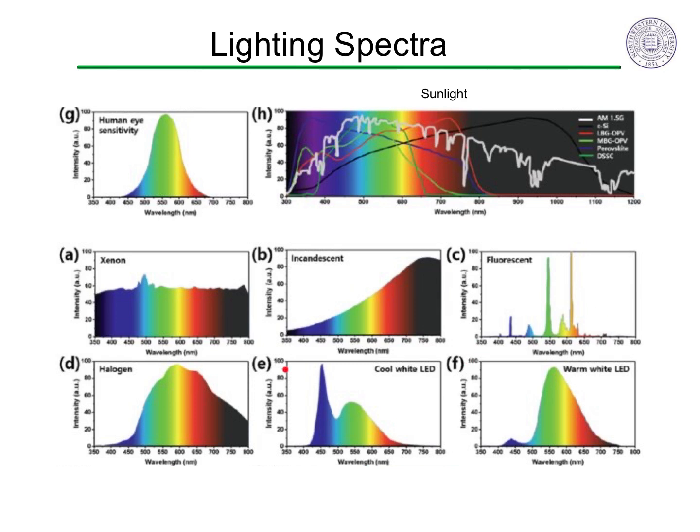LEDs very efficiently produce a narrow range of light determined by the band gap that also requires a phosphor to make white light. Cool white LEDs have a blue LED giving a narrow spectrum of blue light that also excites a phosphor to produce a broadband spectrum around yellow light. Warm white LEDs have more phosphor, particularly in the red, which makes them somewhat lower efficiency.